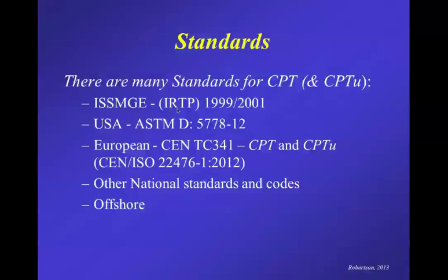So often has that acronym IRTP, International Reference Test Procedure, published in '99, then republished in 2001. In the US, of course, ASTM D5778, recently updated in 2012, with some very minor updates added to it. And then in Europe, they have their Eurocode, and then they also have their series of CEN standards or ISO standards. And there's a recent one that was also updated in 2012. And all three of these cover both CPT and CPTU with pore pressure measurements.